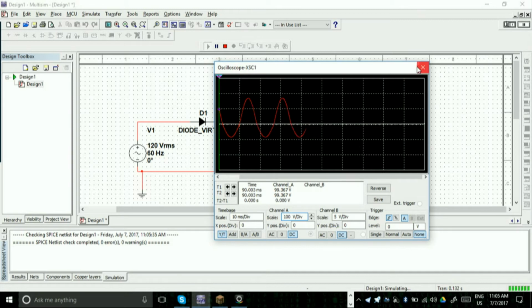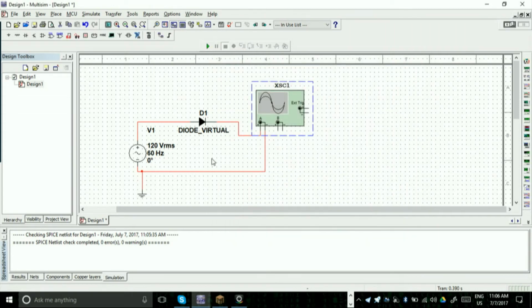However, it's not rectifying completely. And why? Because you have this here. So a little bit leaks out. A little bit of the power leaks through. That's why you don't see one diode on power adapters. They usually use 2 diodes, or the most common case, they use up to 4 diodes to create what they call a full bridge rectifier. It's all in the video that I left in the description.